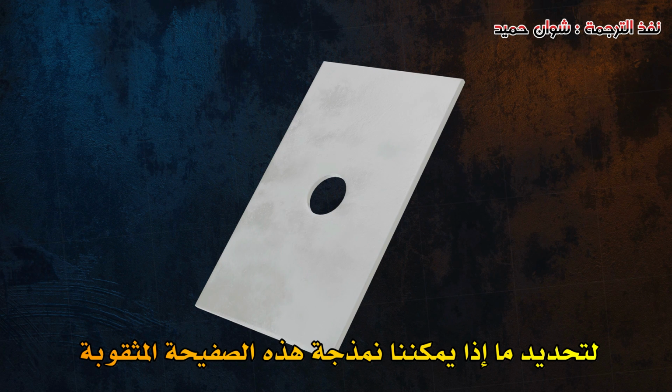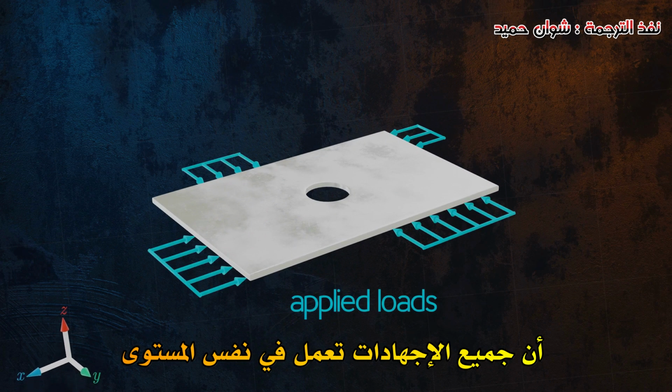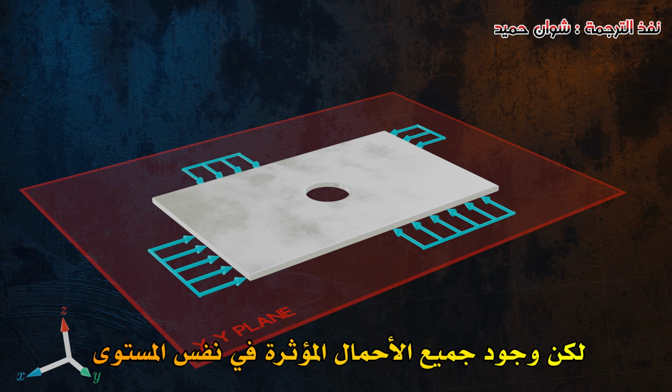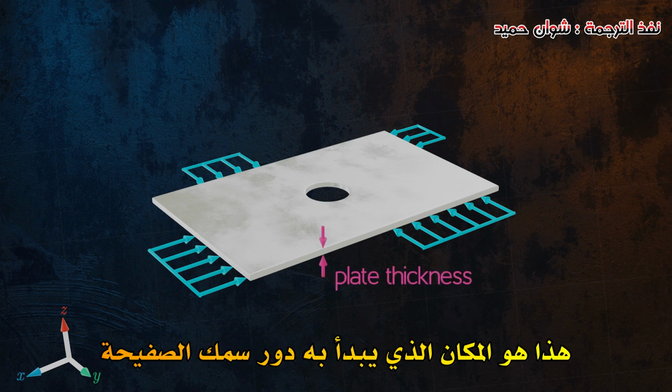To determine whether we could model this perforated plate using plane stress assumptions, we need to see whether it is reasonable to assume that all stresses are acting in the same plane. All of the loads are applied in the same plane, the XY plane, so that's a good start. But having all loads acting in the same plane is not enough for the plane stress condition to be met, as we could still have stresses in the Z direction. This is where the thickness of the plate comes into it.